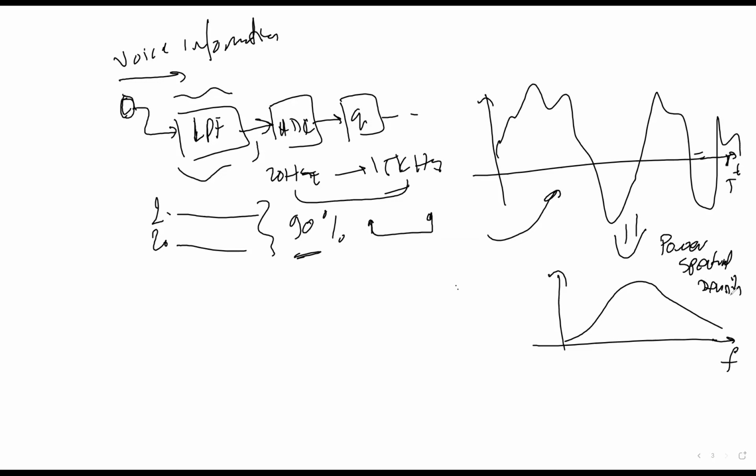Now we have this signal x in time, x of t, and then we have the same signal in frequency, x of f. Now I need 90% of the signal. Maybe I can find that the 90% of the signal will be from f1 up to f2. Actually, in wireless communication, for a human voice, 4 kilohertz contains around 90% of the information of the voice. So you don't need to send all these 15 kilohertz, only 4 kilohertz is enough.